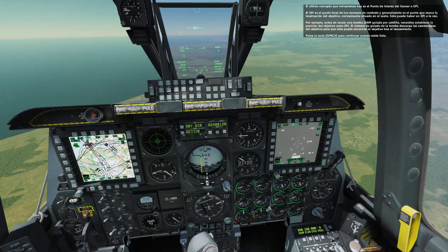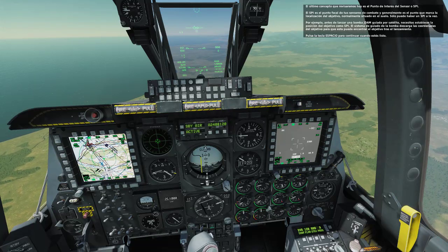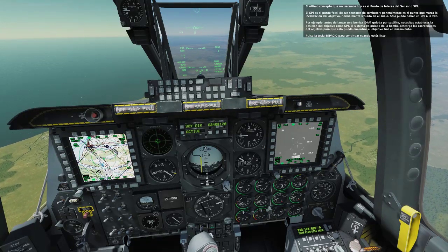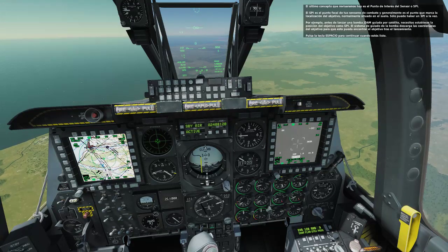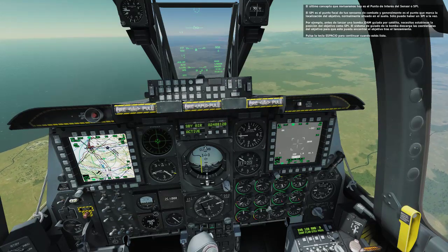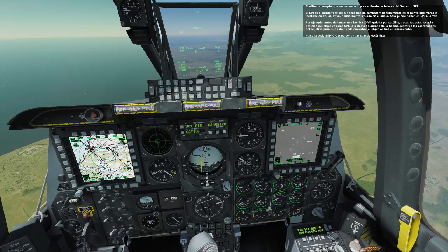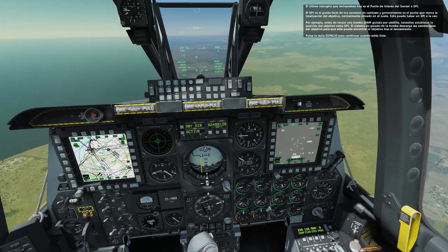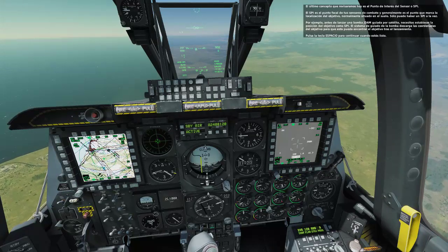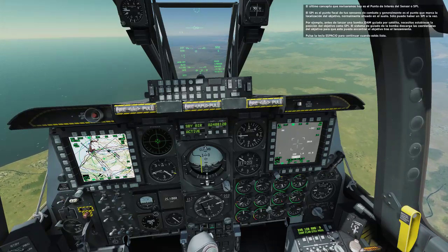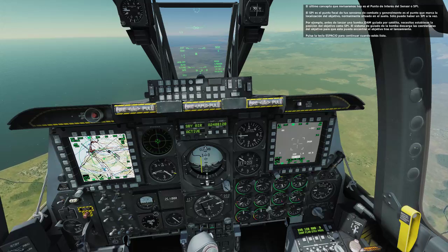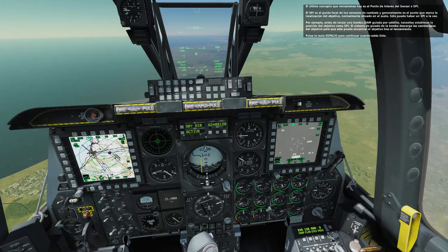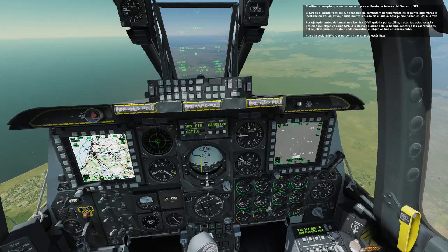The final concept we'll discuss today is the Sensor Point of Interest, or SPI. The SPI is the focal point of your combat sensors and is generally the point marking the location of the target, usually set on the ground. There can only be one SPI at a time. For example, before dropping a satellite-guided JDAM bomb, you need to set the target's position as a SPI. The target's coordinates are then downloaded by the bomb's guidance system to allow it to find the target after release. Press the spacebar key to proceed when ready.